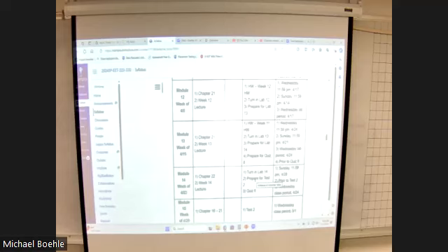Resonance. That's right. So one of the neat things about circuits that have both capacitors and inductors in them is that whole reactance thing I was talking about, created a phase shift. Well, it so happens that one of them creates a phase shift 90 degrees one way. The other one creates a phase shift 90 degrees the other way. Well, what's that? That's 180 degrees. And so we actually have conditions called resonance where the amount of reactance cancels out.